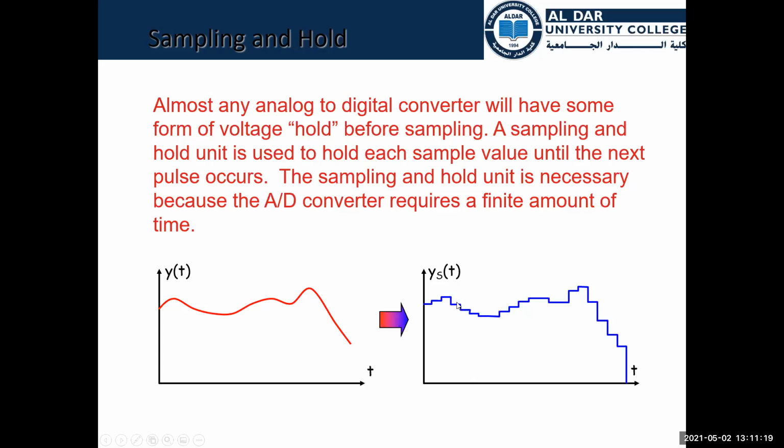This will create a very distorted signal. I don't want to jump down; I just want to continue from the last place I was. This job is done by the sample and hold unit. We just want to keep the voltage at the higher level and jump to the next level, not jump to zero and then quit.